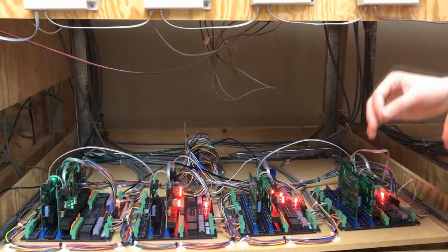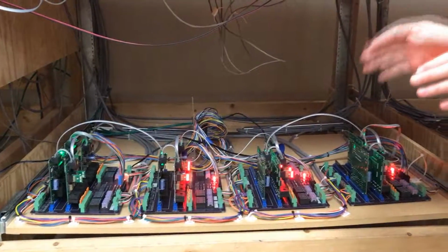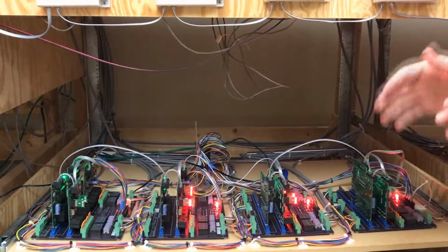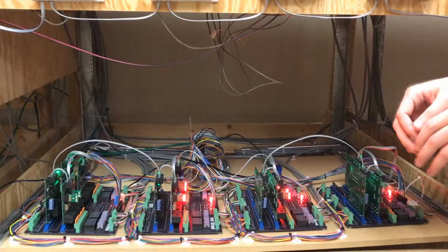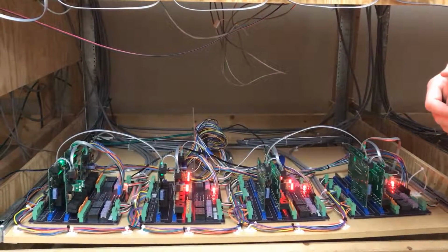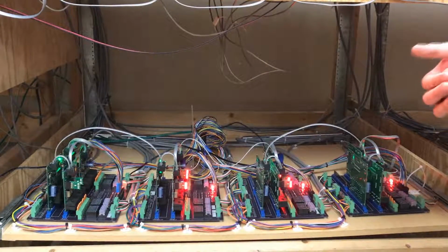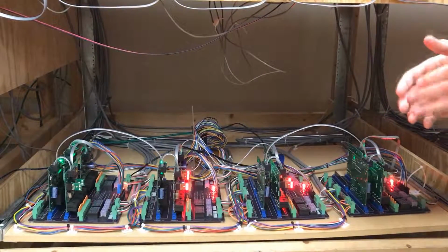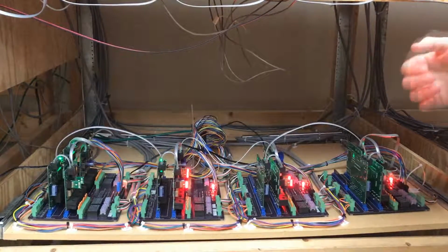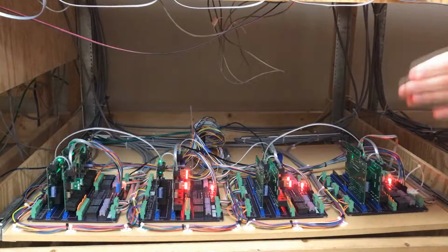This may have been enough to model positive train control, however a problem was soon discovered. Looking underneath the current setup, you can see that there is a lot of circuitry and wires hooked up. When increasing the complexity and length of the track, it was soon realized that power on the rails was dissipating to a point where it was not giving enough power to each train. So it was necessary to divide up the track into sections and have all this circuitry used to make sure each divided section of track is providing enough power. However, this does not solve the problem.